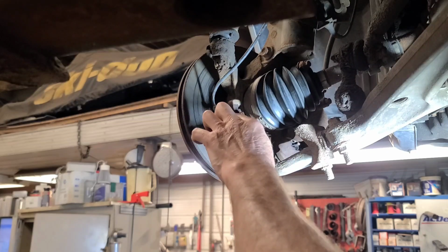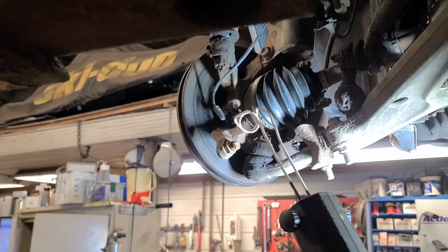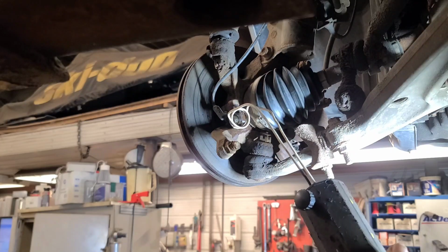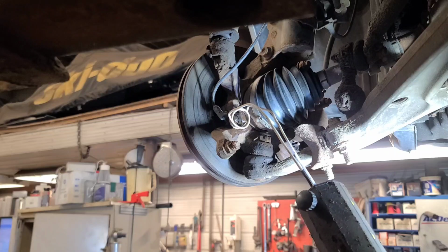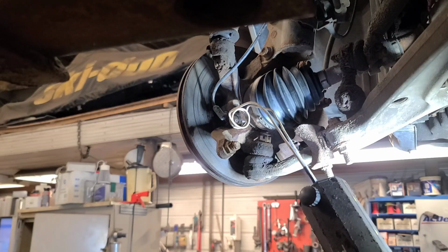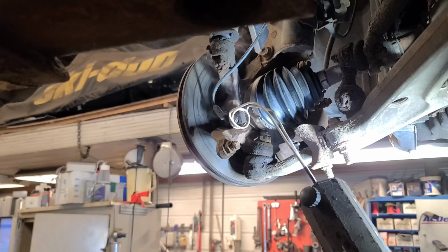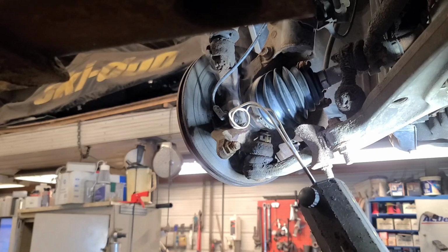So we have to remove this 12mm headed bolt, and it's going to break off. I can tell by the pressure I was putting on it. So I'm going to use a magnetic induction heater to heat this ear up. It might melt the sensor, but I really don't care. I just don't want to burn the boot, the CV boot right next to it. I sprayed it with penetrating fluid. These things are pretty handy. No open flame.